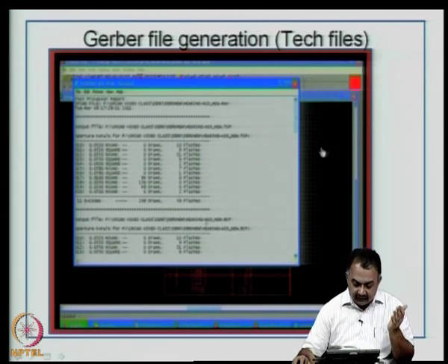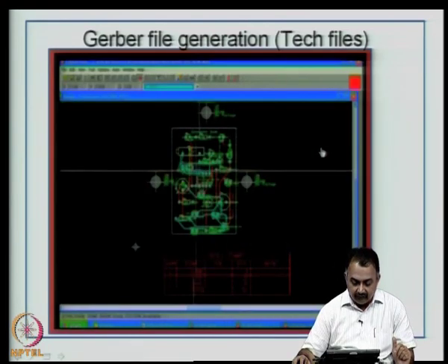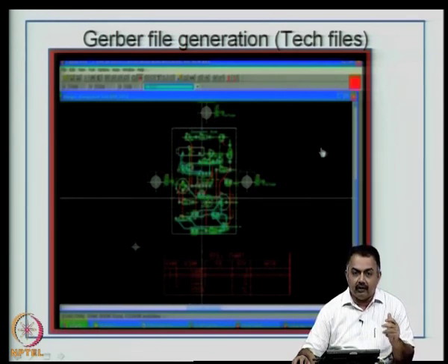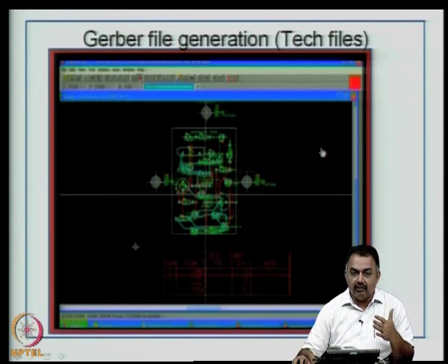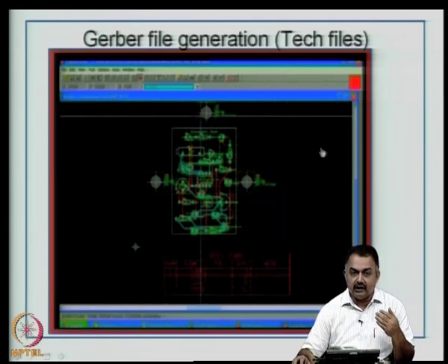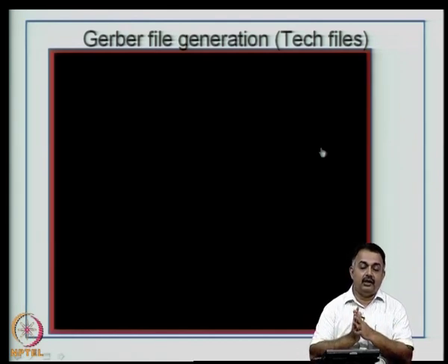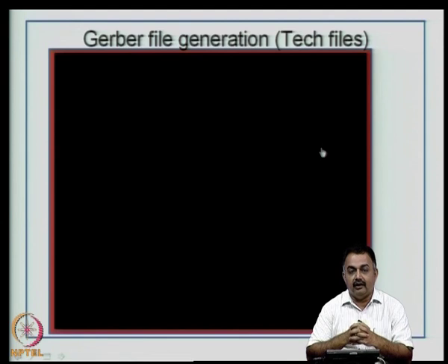So, you can send the set of information anywhere and get your masks done. Then after this you can also create a drill file. So, drill file is based on Excellon format, and a drill file typically you will see XY coordinates of the drill mentioned, the number of drill bits used and the sizes of each of the drill bits used, including the vias and the pads and so on. So, this is a very good documentation that you have to correctly generate before you send it off by electronic means to the manufacturer.